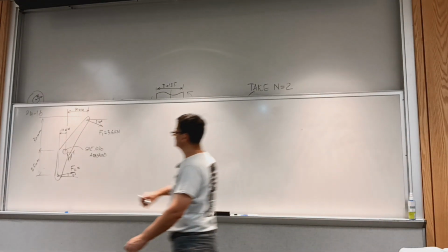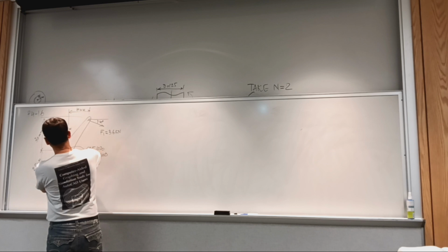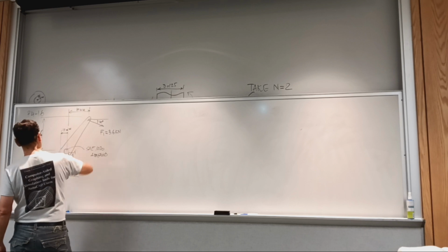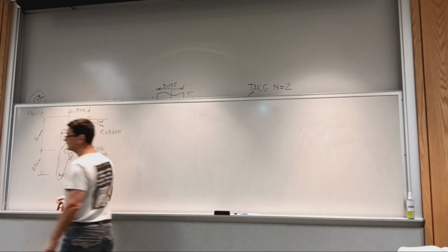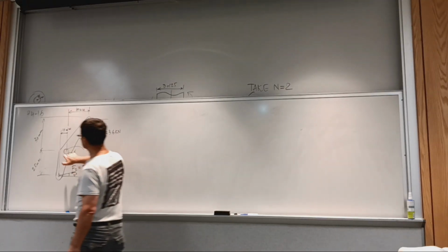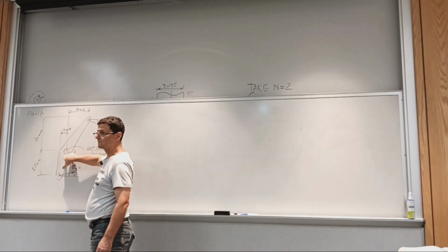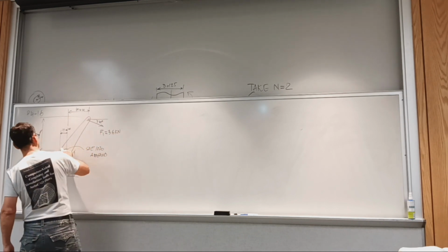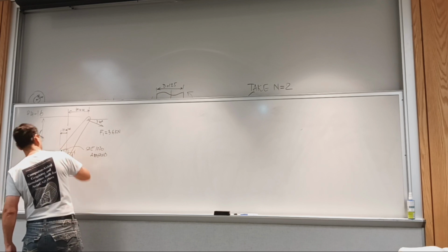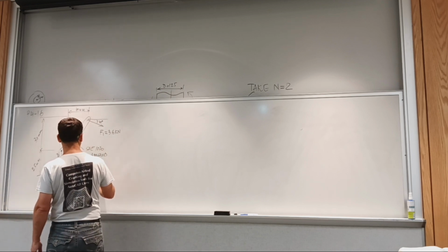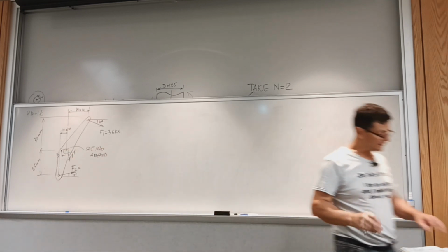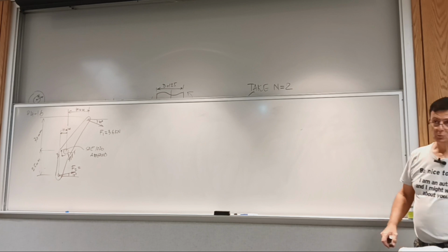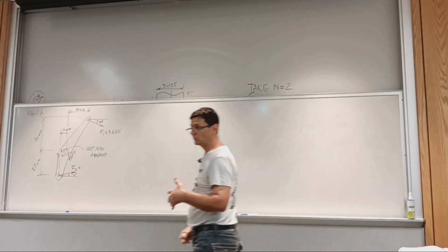Okay, so we need to calculate this force, and once we know the two forces, then we can draw a free body. So some moments about the pin, and then we're going to draw a free body diagram for the entire bell crank, find reactions at the pin, and then their resultant, and then divide by the area. Well, we need to calculate the diameter. So what's the diameter D of the pin? Okay. And it says the loads are repeated many times. So we need to go to what the recommendations are when you have loads that are repeated many times.